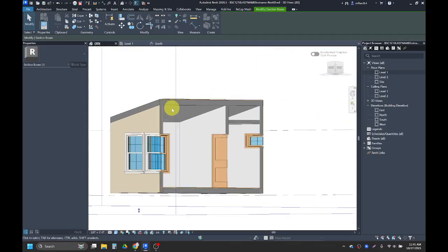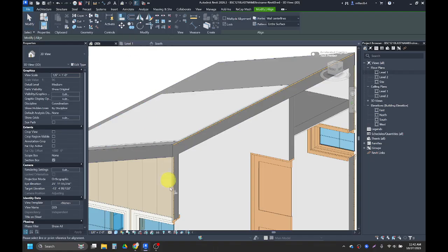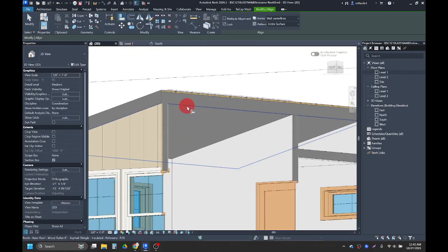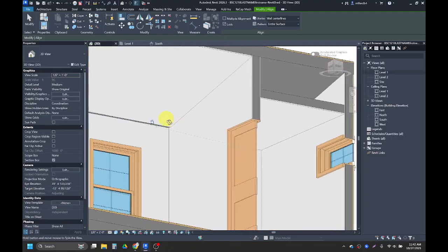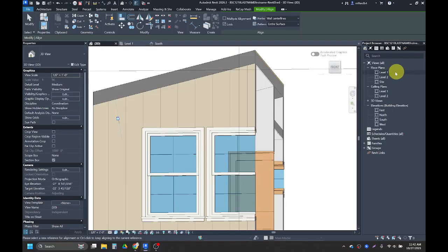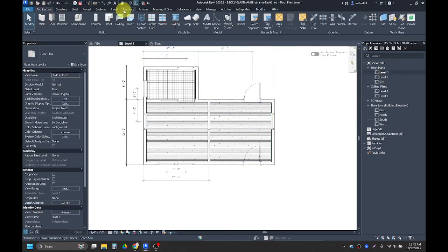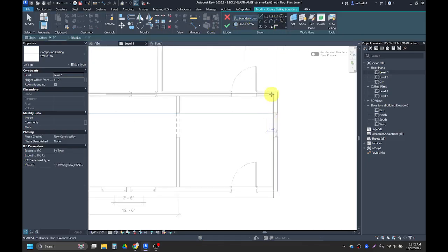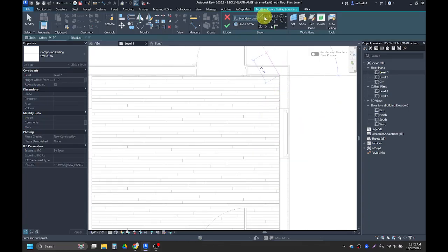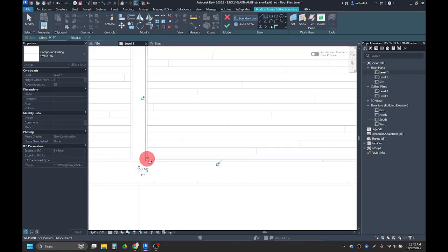Boom. Oh, see, yep. For some reason, it's hanging out all the way up here on top of my ceiling. So now I should be able to do an align of this roof's face to this ceiling's face, and that way my ceiling is inside my building. Let's go back into our level 1 floor plan. And let's do another ceiling. So again, that's going to be the ceiling tool. We don't want automatic. We're going to do a sketch. Whoops. Let me click the rectangle tool from face to face.